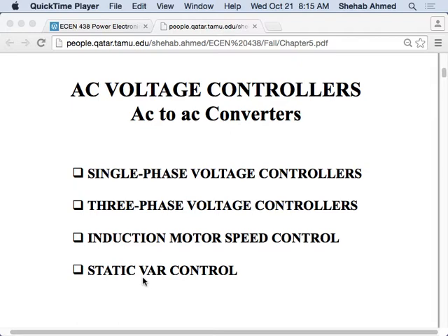To do that, if the system is highly inductive, what would you do? Add some capacitance. It's highly inductive, so the current is highly lagging. So you add some capacitances in different places in the system. How do you locate these capacitances? That depends on how much reactive power. If a portion of the power system is drawing too much reactive power, that's where you want to locate the capacitors, not in a place where loads are not consuming a lot of reactive power. So placing these capacitors is a different issue, and we don't discuss that.